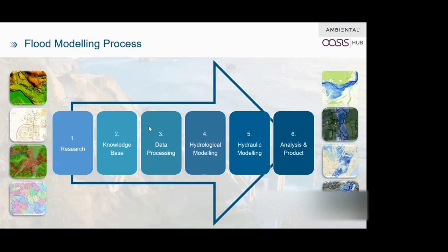The next stage involves the analysis and pre-processing of the numerous input data sets using GIS to ensure that everything is in a correct and compatible format. This process includes treating the data to remove artifacts that could potentially unrealistically impact the results of our hydraulic modelling, for example. It can also include aligning the format and resolution of data sets from a range of different sources.